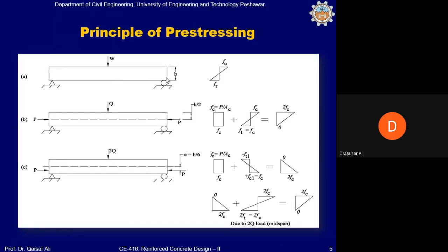This was the case of a reinforced concrete beam. However, now let's say we do not want to reinforce the beam, and we want to pre-compress the beam. Before the application of load Q, the load has not been applied yet, and we pre-compress the beam by applying a force P, as shown in this figure.